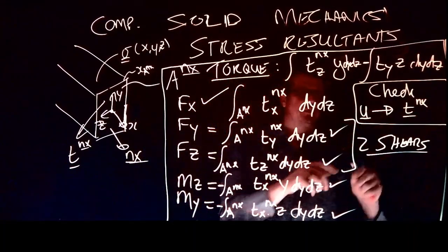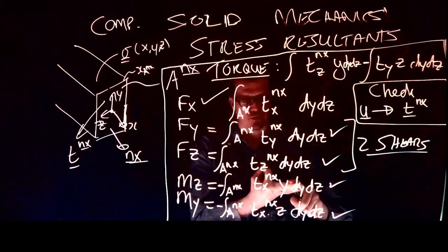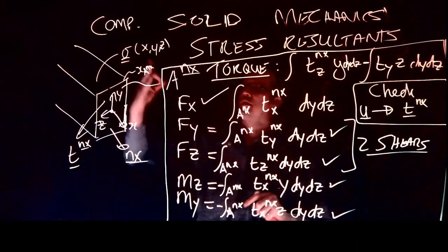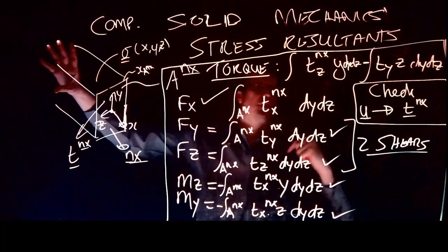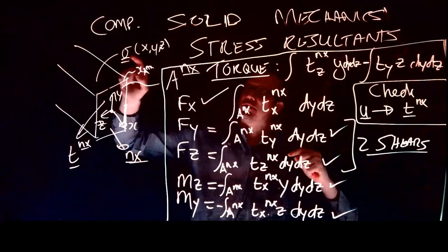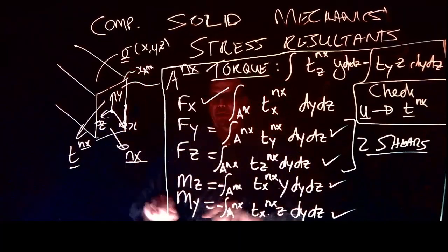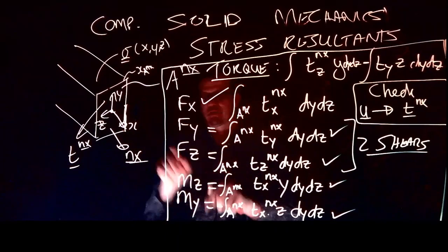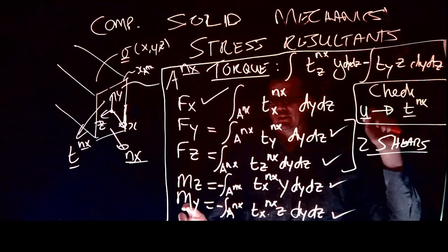Typically, if you give me the displacement field, I can compute the strain, and then I can compute the stress tensor. Now I have the full stress field for that problem. Now I need to check: can I convert this stress field towards tractions, and compute my macroscopic moments and forces on a surface, and does it make sense based on the problem that was stated?